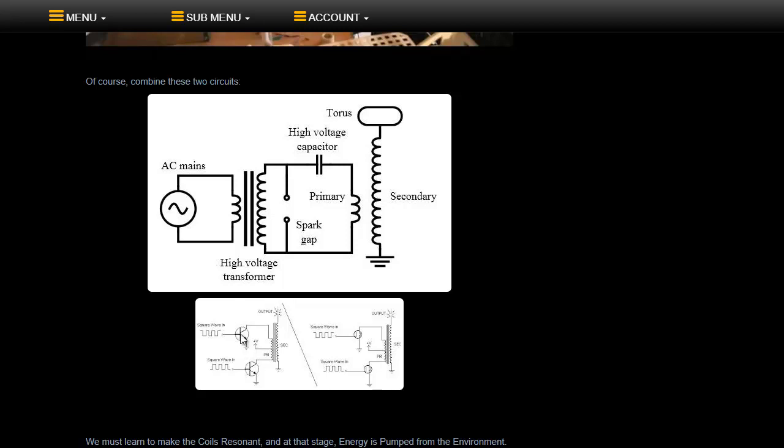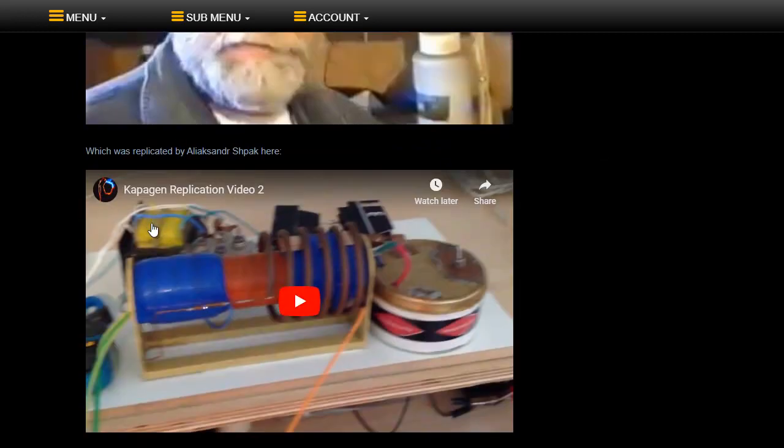Okay, if you replace the AC source with push-pull transformer here with a couple of MOSFETs, you might need a reasonably large ferrite core to get the pulsing going, so that you're not saturating the core and doing all sorts of yucky things. Obviously you've got to get this transformer working at the maximum efficiency, so you're going to need a reasonably large core here to make sure the core doesn't saturate at a certain power level, certain wattage.